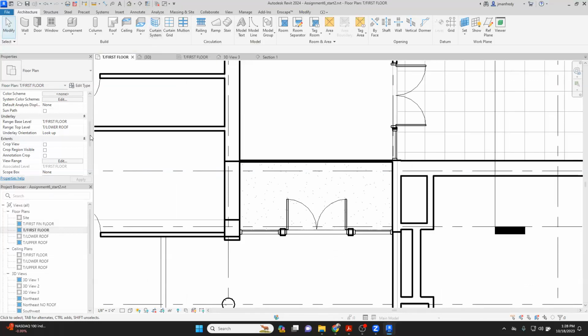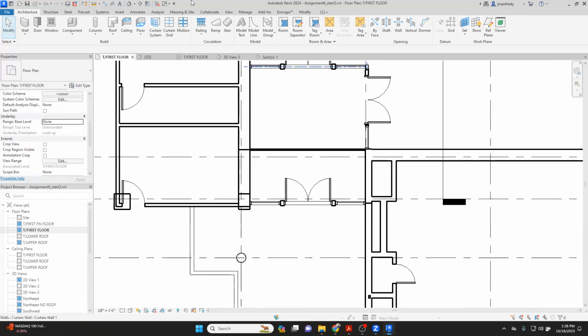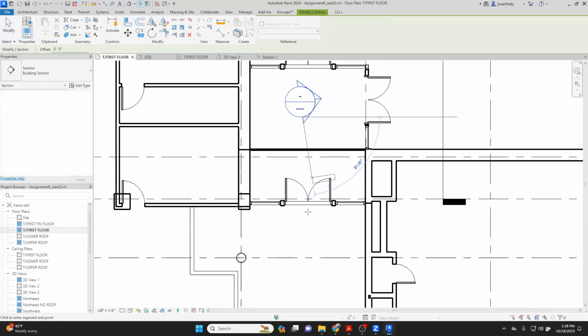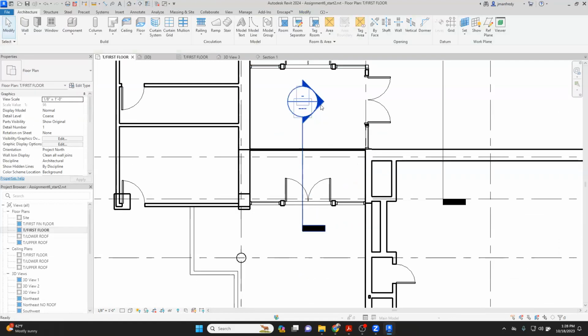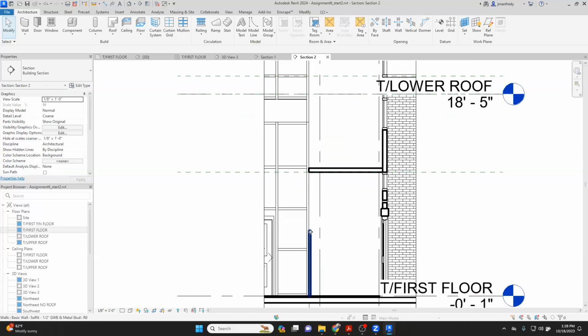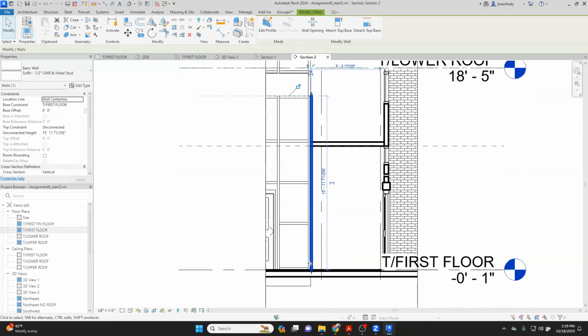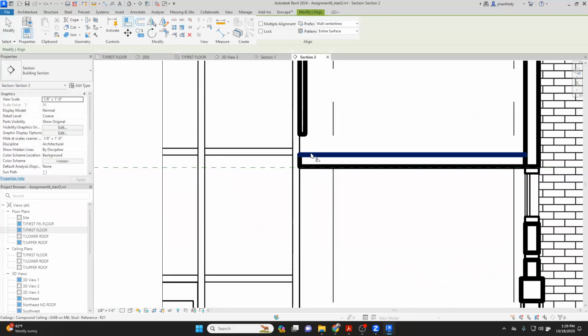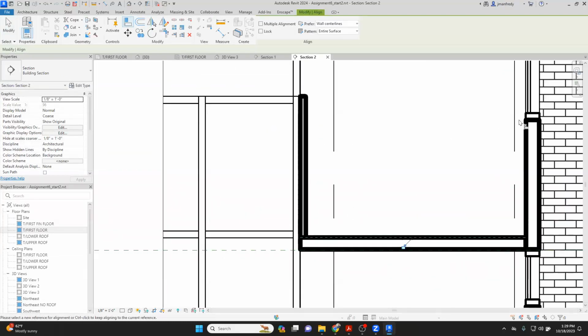That's what a section's for. Don't forget to turn off underlay. Always turn off underlay before you leave. And just cut a section through it to make sure it's in the right spot. This soffit is up here somewhere, sitting on top of that ceiling. So I can use the align command and line it up with this edge, with that top. Oops, don't grab the wrong thing.